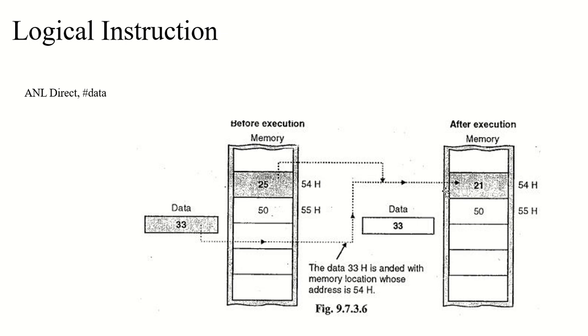The output is 21h. It is getting stored at 54h because earlier we considered memory location 54h for collecting the data, and because we are considering direct addressing mode, and the destination is this 54h with direct addressing mode, the output will be stored in 54h itself. Pretty much clear.